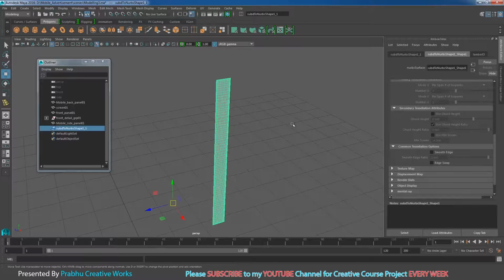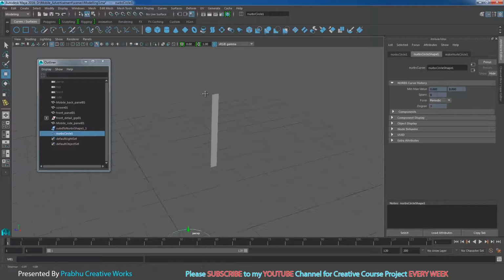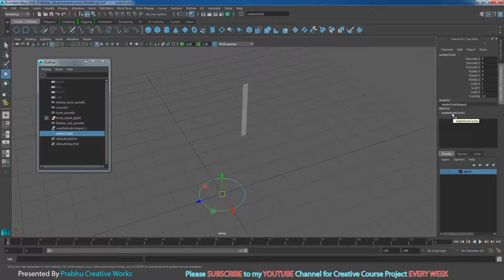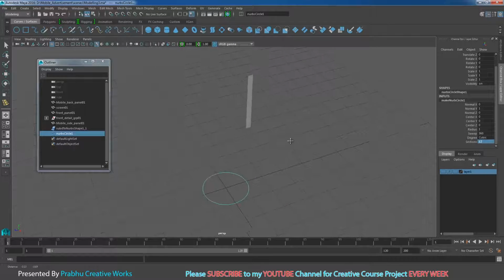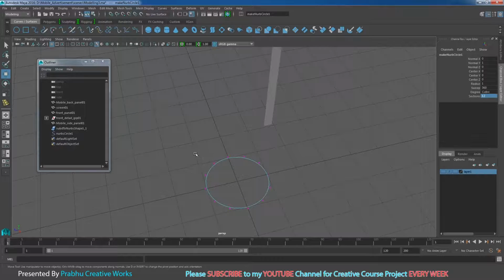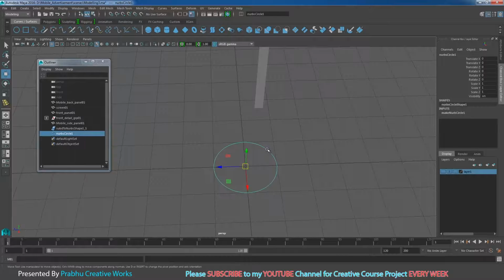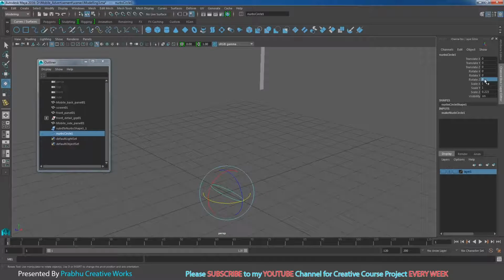Now we want to make a hole on this surface. Using curve tools, click on NURBS circle over here. It will automatically be created in the center of the grid. Go to channel box and layer editor, expand this one and give sections 12 over here. Right click and choose control vertex. I will select all the control vertices over here, press R and scale in Z. You want to rotate Z by 90.